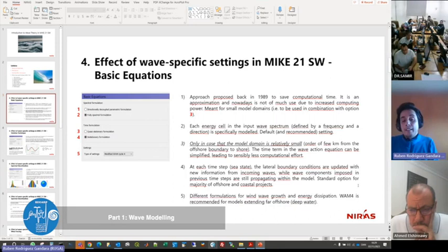Basically, the thing is that deep water and shallow water are relative concepts. For example, if I have 1,000 meters of water depth and a wave height of 1 meter, that ratio is so small that the 1 meter wave is in deep water. It's so small compared to the water depth that it doesn't feel any effect.